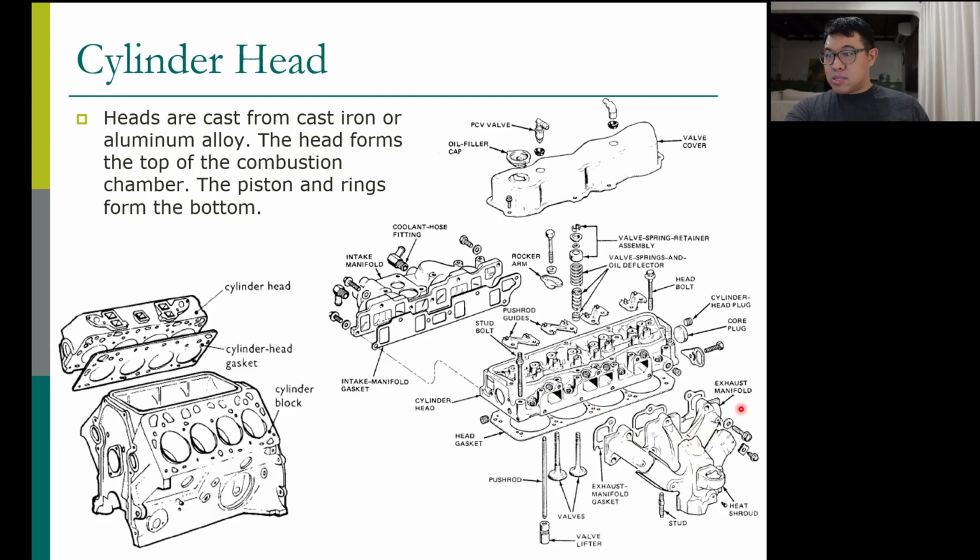What else? It also has the valve train mechanism on this cylinder head that controls the valves. So most of the engine control, air fuel mixture going in, exhaust going out, the valve opening, are controlled inside this cylinder head. So up here, on top of the cylinder head, we install the valve trains.